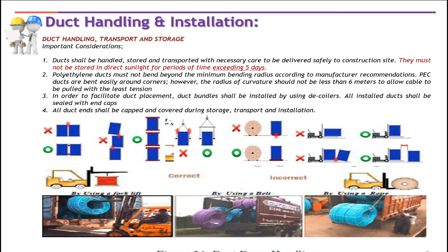All materials should be handled with care during transport, and ducts shall not be stored in direct sunlight for more than 5 days. Always use a decoiler to facilitate the duct placement. All ducts shall be capped and covered during storage, transport, and installation.